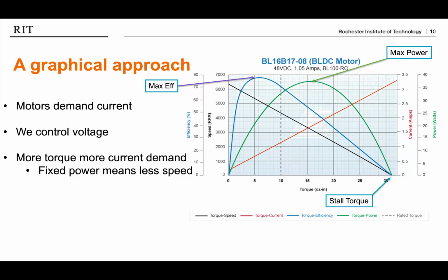If you have a system that's going to spend reasonable portions of its life coming up to and running around this max power point, that's reasonable, especially if this is a motor that doesn't move. And hopefully, no one said, well, I will design and pick a motor so that my nominal torque sits out here at a stall torque. That would be very bad and would shorten the life of your motor.